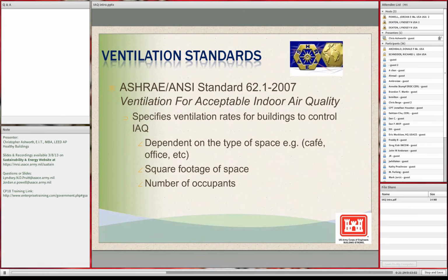And we're talking about ventilation. The main standard that everyone uses is ASHRAE 62. I referenced 2007, but there's 2009, and there are various updates that continually get managed. This really is right now the baseline of LEED and other building codes, etc. Obviously, I'm assuming most people know who ASHRAE is, the American Society of Heating, Refrigeration, and Air Conditioning Engineers.